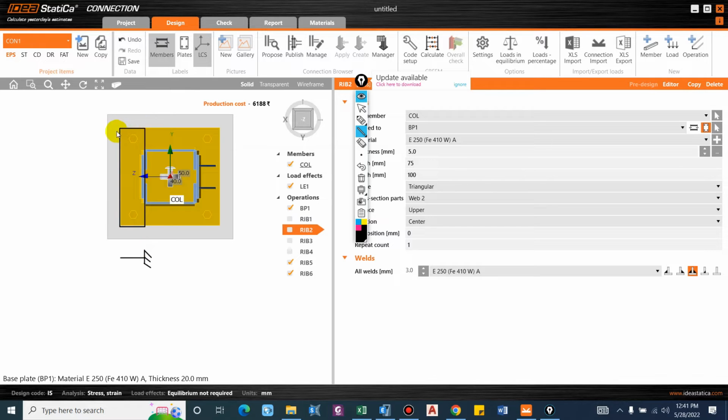So this is a cantilever side, this is also a cantilever side, this is also a cantilever side. So this is the effective length. So with this we are calculating the thickness of plate required. Now if I provide a stiffener, for example over here, you can see that it is divided into a number of members. For example, let us take this.